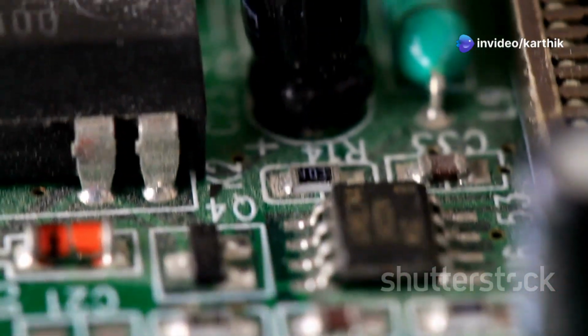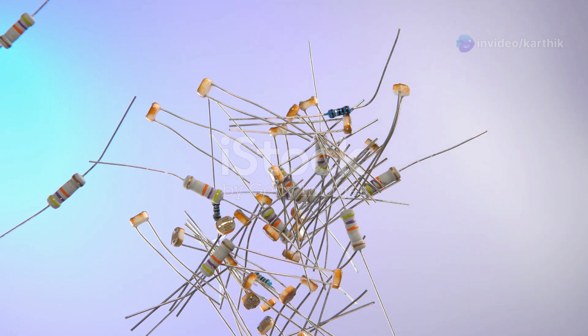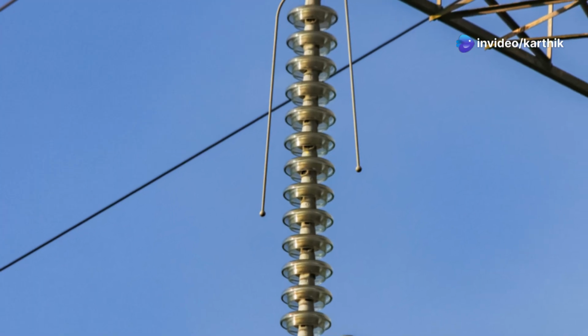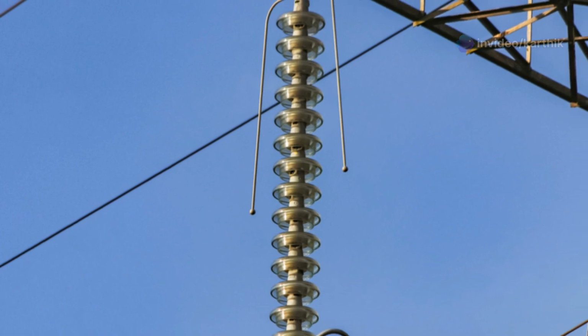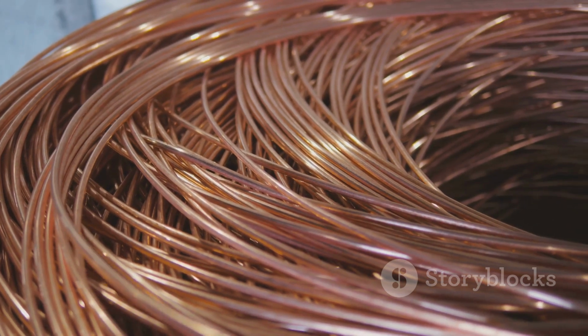The resistance of a material is determined by its inherent properties and physical dimensions. Different materials have different atomic structures, affecting how easily electrons can flow through them. Resistivity is an intrinsic property of a material that quantifies its resistance to electrical current. Materials with high resistivity, like ceramics, are good insulators. Materials with low resistivity, like copper, are good conductors.